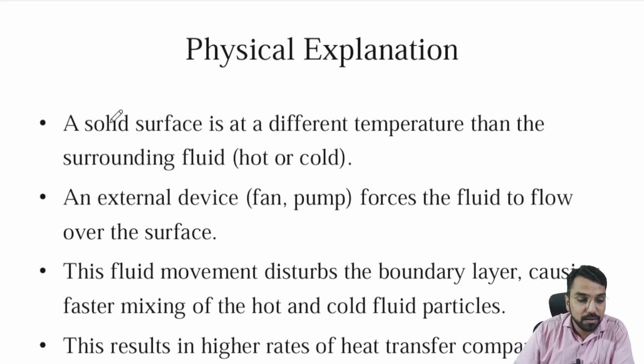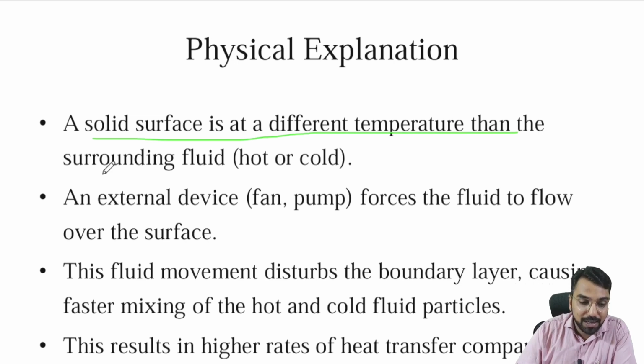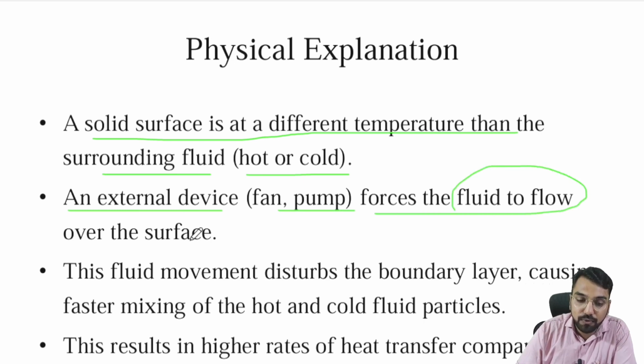A solid surface is at a different temperature than the surroundings, either cold or hot. An external device, a pump or fan, forces the fluid to flow over the surface, and this fluid movement disturbs the boundary layer and causes mixing of hot and cold fluid particles.